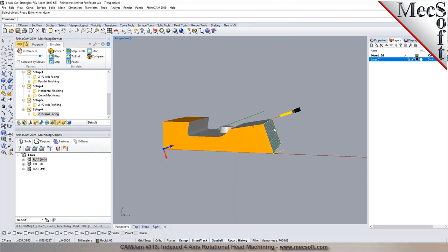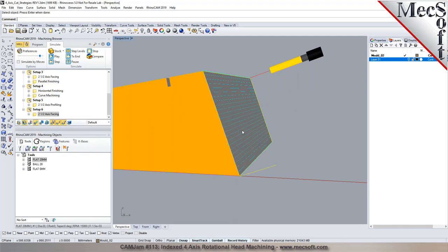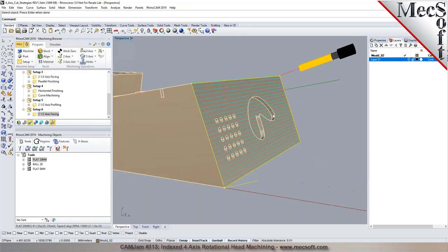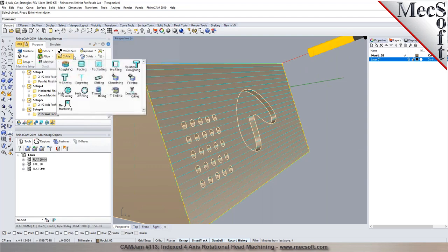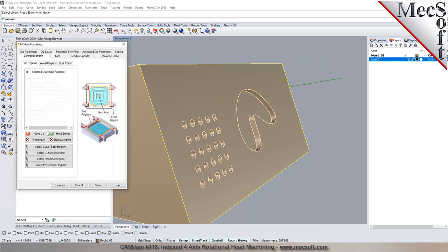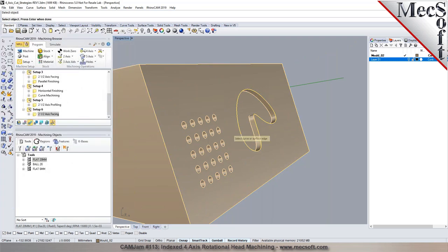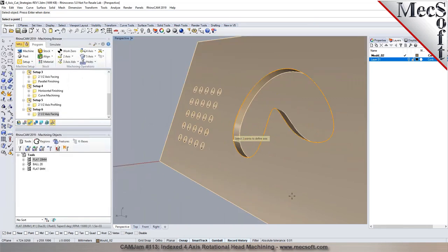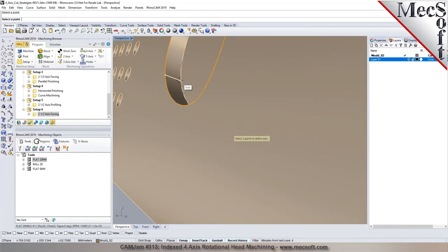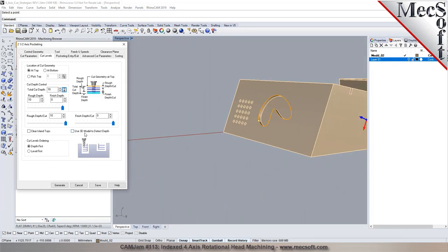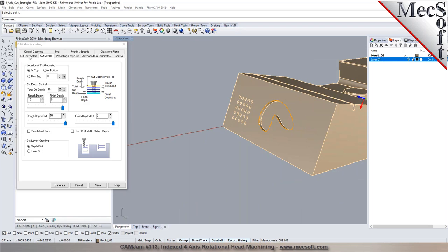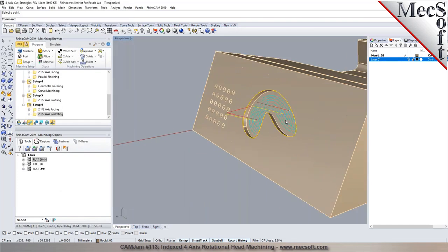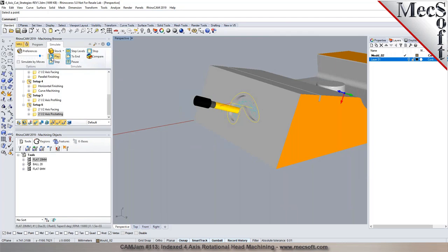If you wanted to do a roughing operation, you could do it. So to do like a re-roughing to remove the excess symmetry on this orientation. Yep. And once you're through with the facing, you want to do this pocket in here, 2-axis pocketing. You can pick this edge. And then I could still do the same cutter. And then all I had to do is pick the depth in here. Okay. I can also say determine using 3D models, so it'll figure out how deep the pocket is. If you want to do rough and finishing all in one operation, you can set the stock to 0. So that gives you the pocket operation.